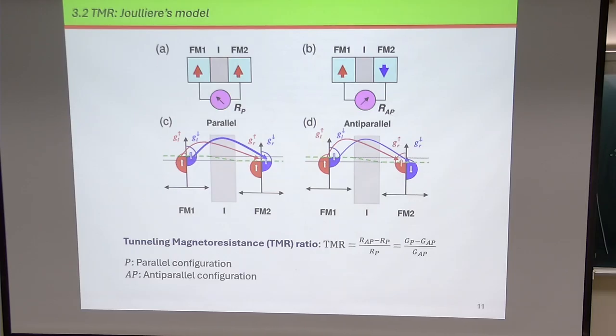So current equal to something times voltage. What is this something here? A resistance, if I remember Ohm's law, this will be 1 over R. So what is 1 over R? Conductance, okay? So I will have then the conductance times the voltage. So I can then find the conductance from this equation and use it in my definition here of the tunneling magnetoresistance, TMR. So I can put it in there and then see what is the TMR.